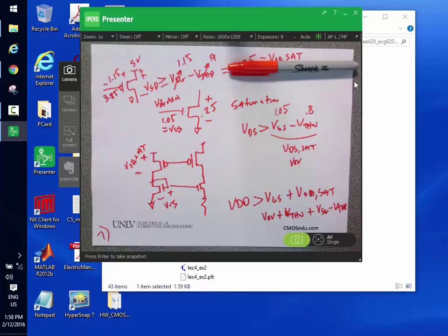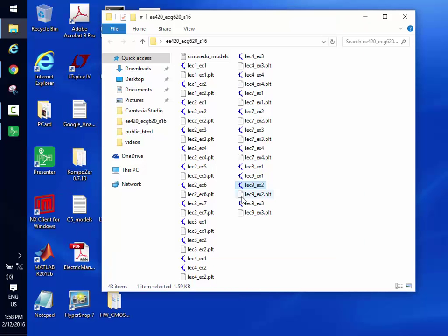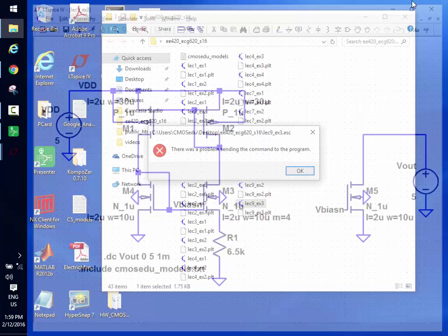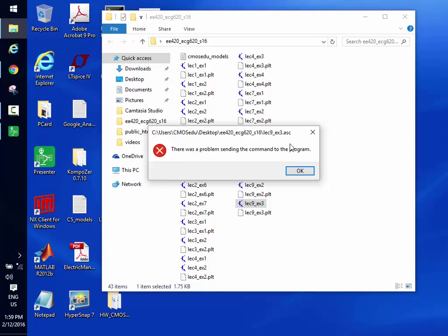Look at the following. Let's see if I can make this break. And this, I will tell you, when you do design, the startup circuit is often neglected because once the circuit starts up and you're not in the state that you want to be, it doesn't do anything. So people tend to neglect it, and then when they get their silicon out of the fab and they test it, they find out, hey, this doesn't work. And then they have to fiddle with the power supply to flick it to get it to start up, and that's not good. So it's important that you spend time on this. Okay? You know what? What the heck's going on here?